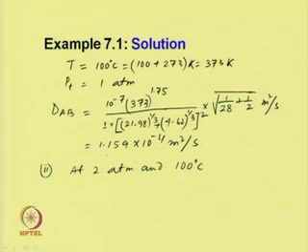So, keeping all the properties same for the components in problem 2, at constant temperature, which is 100 degree centigrade, the diffusivity DAB from the Fuller's equation is inversely proportional to the total pressure.